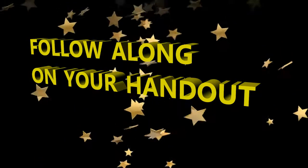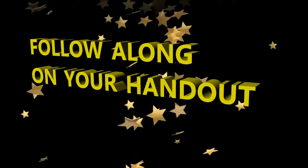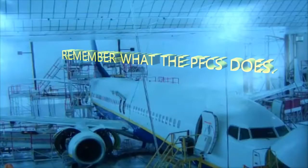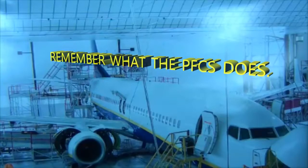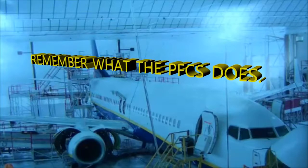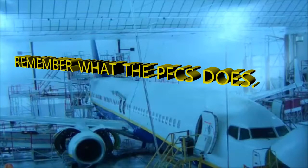All right, let's go ahead and go back to our lesson here. Just remember that Nav Error Data Disagree will show up if you have a failure of one of the Ailerons. And also, the primary flight control system is used to consolidate the parameters of those Ailerons to the primary computers, and that's actually used to compute the laws. So it's really critical the way that it's taking in those sensor inputs and ensuring that it's getting the right data in order to give the commands.